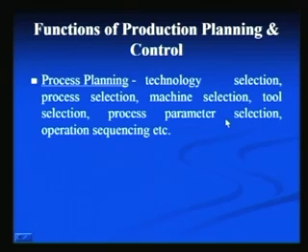And in the same way, we have to sequence the operations which we have already identified. As we know, for the manufacturing of any product, several operations are required to be performed, and it is important to determine the sequence in which those operations should be performed. So, operation sequencing is always important. While determining the operation sequence for a product, we should keep in mind that the total number of tool changeovers should be minimum and the total number of machine changeovers should be minimum, so that the non-productive time added because of machine changeover and tool changeover is minimum. All these aspects are taken into account while going for operation sequencing in process planning.